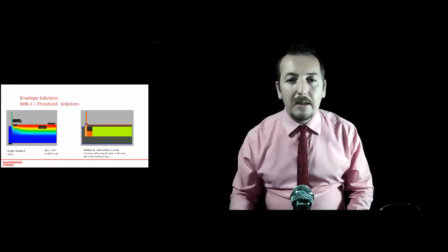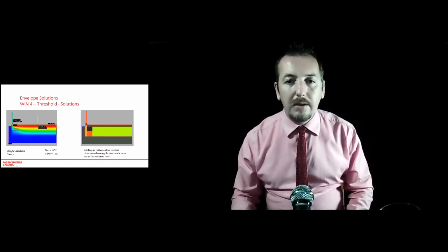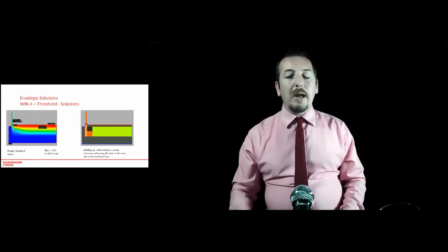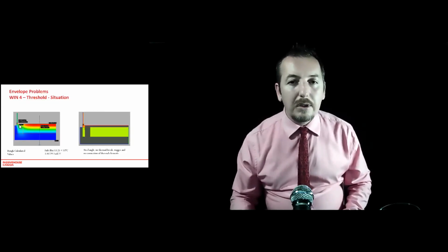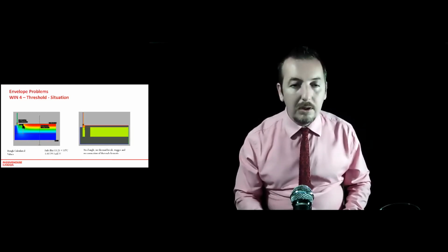Then the updated model was to just build everything up with thermal breaks, make sure that the thermal break in the door threshold aligned with it. And there we have, I think this may be wrong. Maybe it is though, 0.15. But as you can see in our previous slide, the surface temperature, even though it was a decent window, was 13.25.